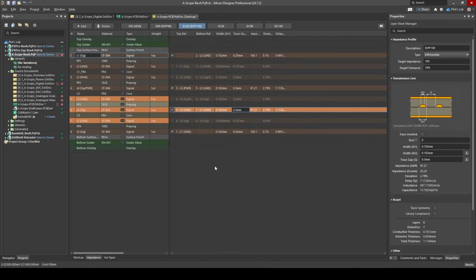So keep in mind, for RGMII, for Gigabit Ethernet, you will need controlled impedance traces in pretty much all cases. So speak to your manufacturer, get yourself a decent stack up, remember ground adjacent to every signal layer and every power layer.